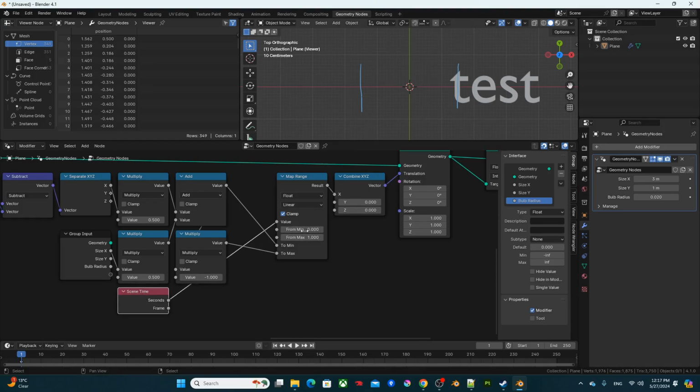And depending on the length of the time that you want, you can make it so it moves over from right to left within whatever time you want. So right now I've set it to 3 seconds, so it's going to take 3 seconds to traverse from starting position to ending position, like so.